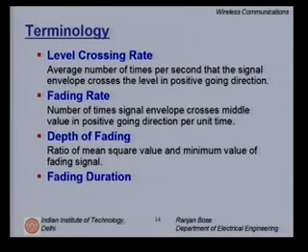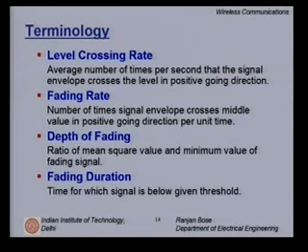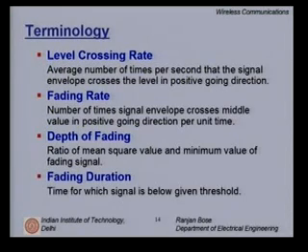Fading duration is the time for which the signal is below a given threshold. Clearly, this threshold that we are talking about is a sensitivity level at the receiver, beyond which we define the signal to be faded. So if my fading duration is long, then I will tend to drop my call.